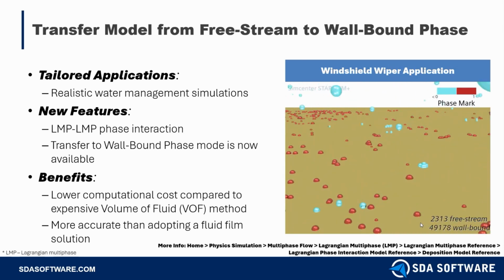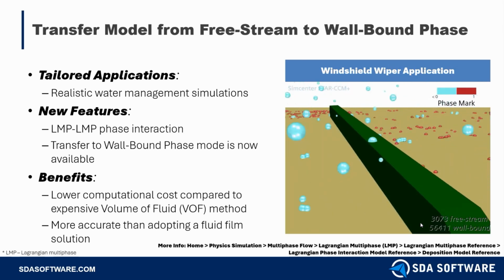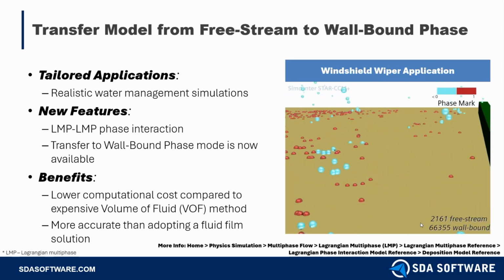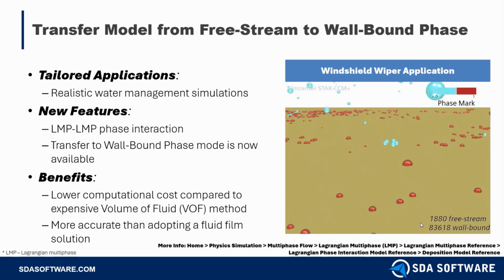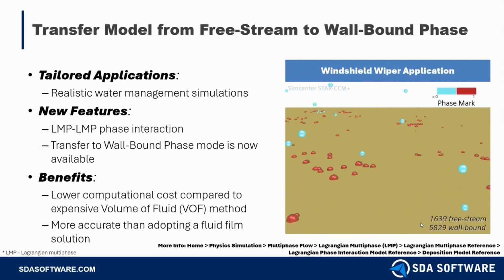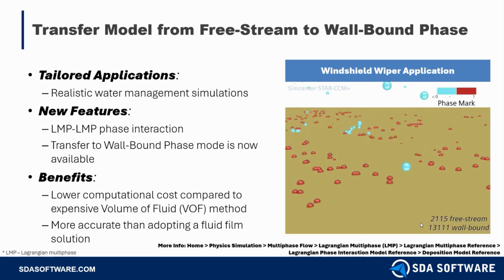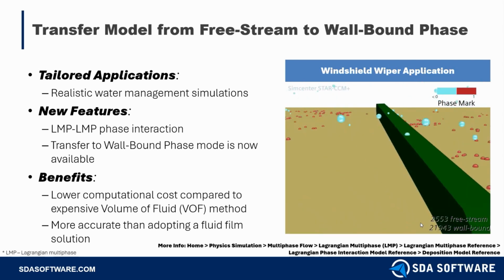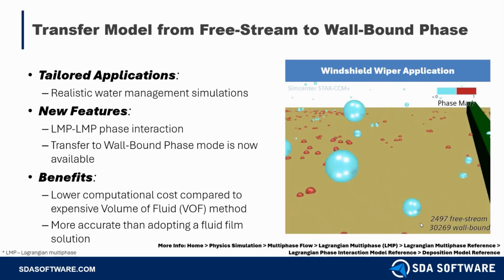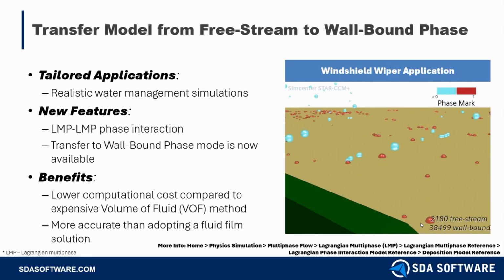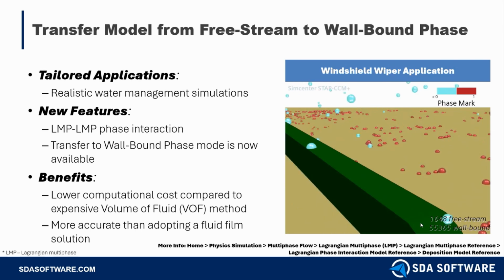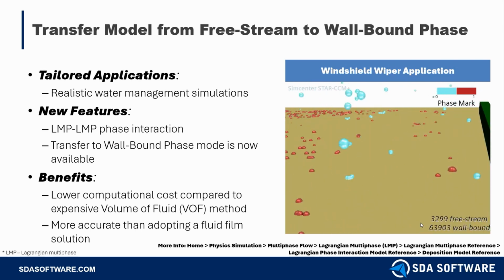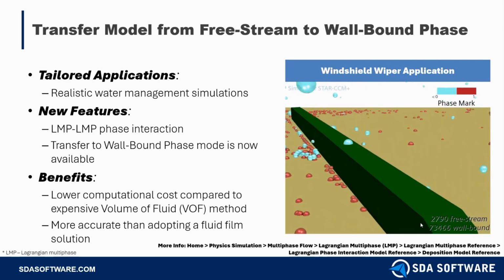Before this update, to simulate this sort of application, users would either need to use the expensive VOF method to resolve all the free surfaces of the droplets, or adopt a fluid film solution with less accuracy. So this new LMP to LMP phase interaction essentially enables realistic water management simulation now with lower computational costs while retaining the high accuracy. And more information on this deposition model can be found in the more info tab as well.